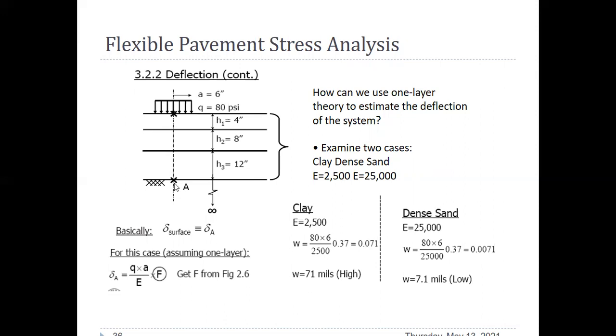So if my subsurface is clay, then the deflection will be 71 mils. And if my subgrade is sand, this deflection will be 7.1 mils.